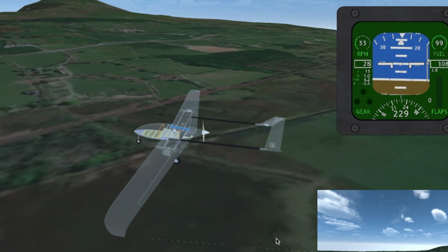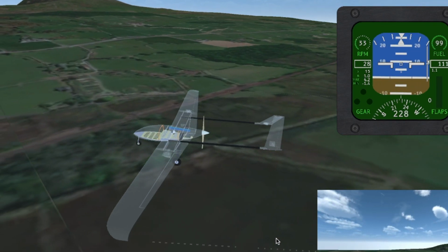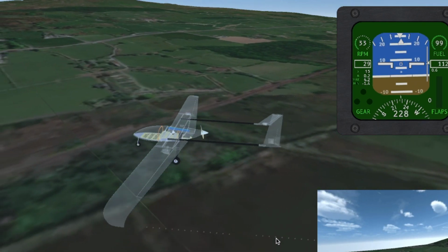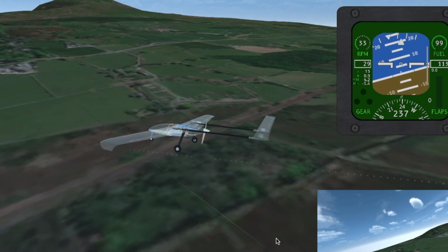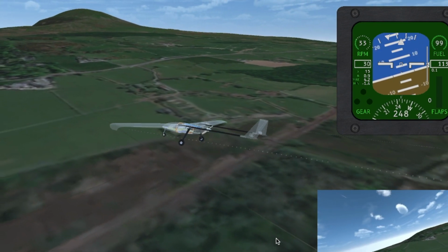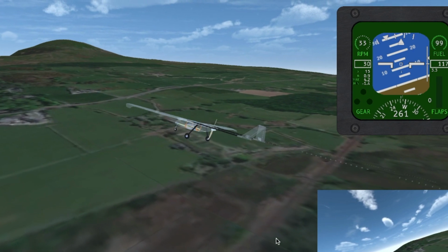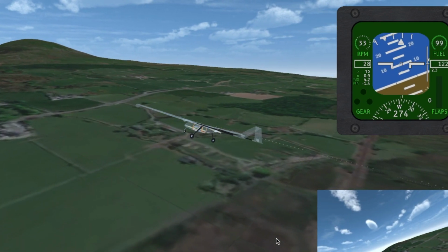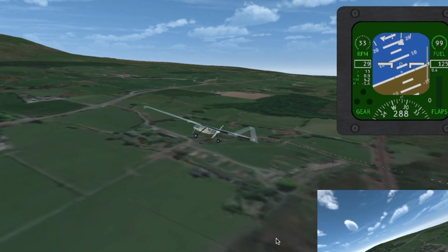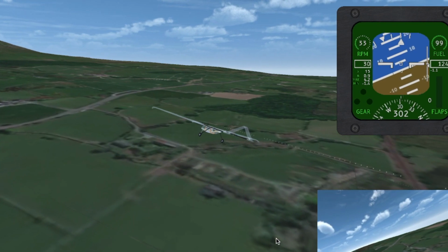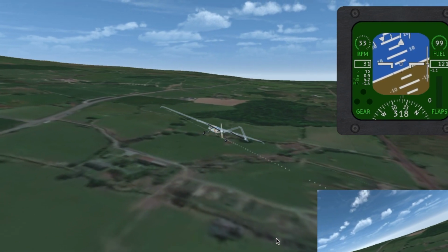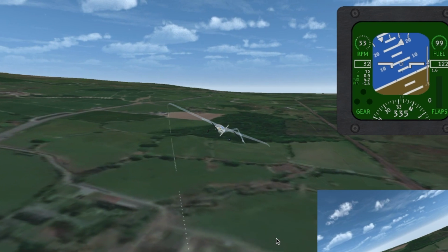Hello there, welcome to a video on Albatross UAV flight test briefing. This video will explore the preliminary tests and assessments carried out on the aircraft to ensure its safety and optimal performance. This video covers the weight and balance test, center of gravity position, flight controls test, wind tunnel test, and other crucial aspects of the aircraft's stability and maneuverability.